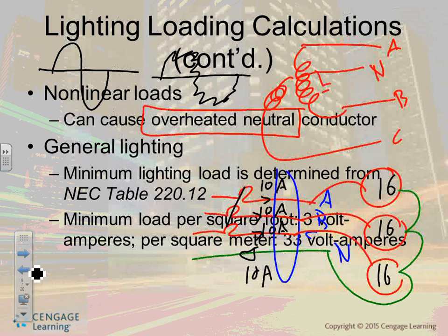Literally. The electronic device utilizes electricity in a nonlinear way. A nonlinear way means it screws up the curves from this shape into this shape. Who cares about curves? Well, all the relationships between the phases will be screwed up. And you end up with a balanced three-phase system with a neutral still carrying the same amount of current as the phases.